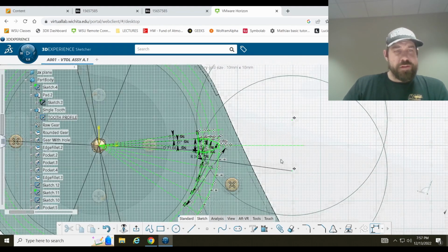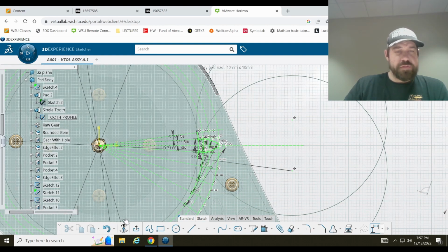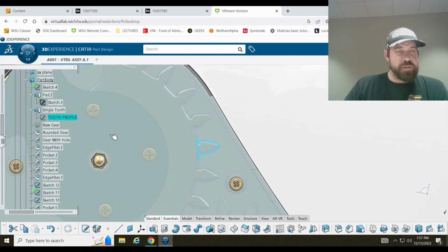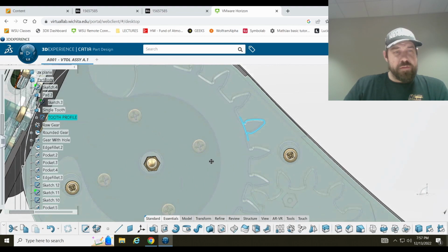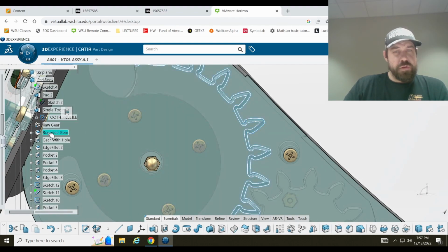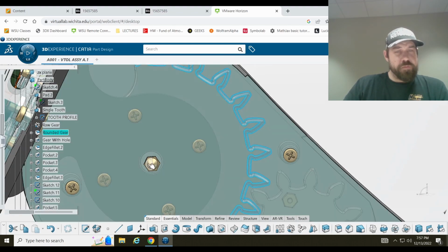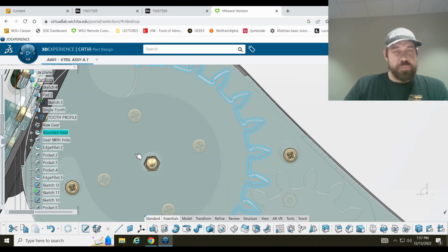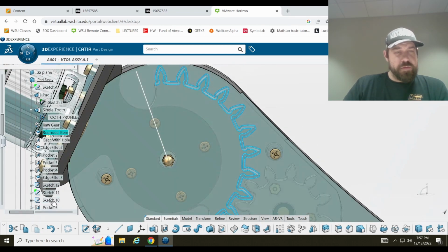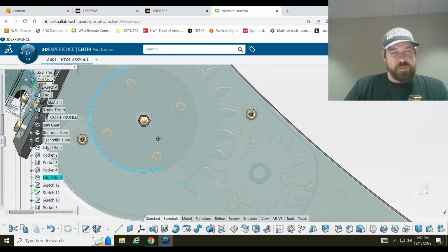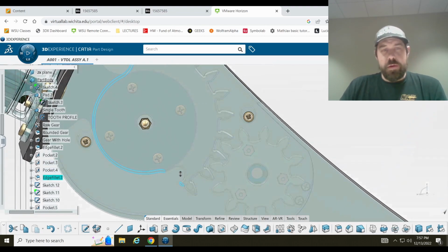So I generated an entire gear from that instead of just generating the 11 teeth. And then I modified that to have the hole in the center the size that I needed it, the other pockets. And then in these other sketches, I'm making more delicate adjustments to the shape of this thing. So we'll look at some of these adjustments in the next section.